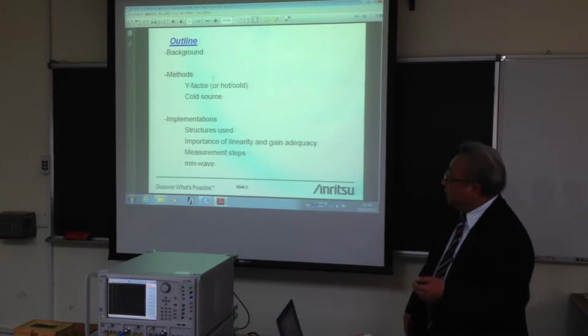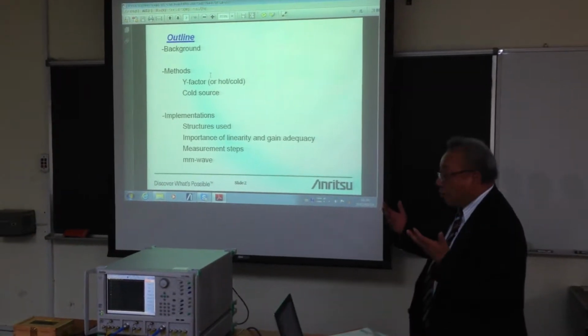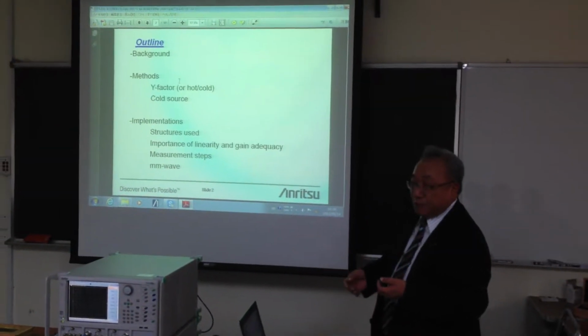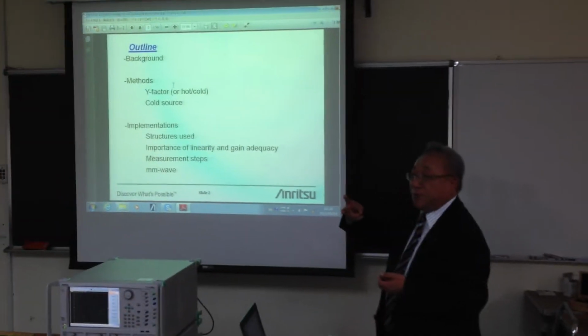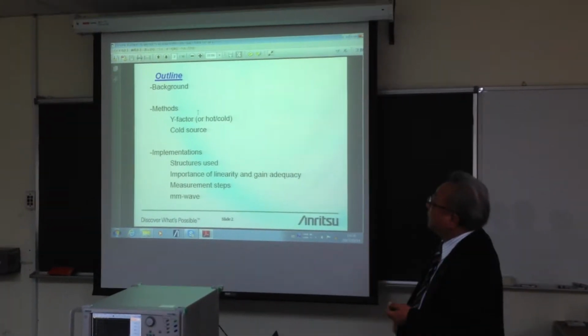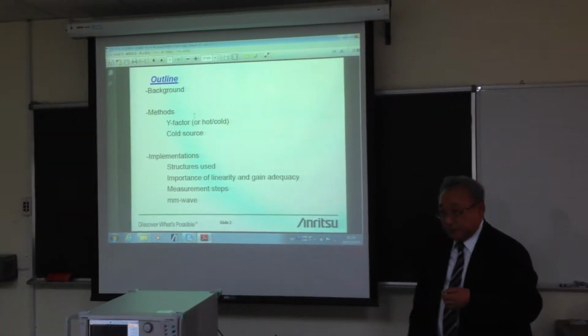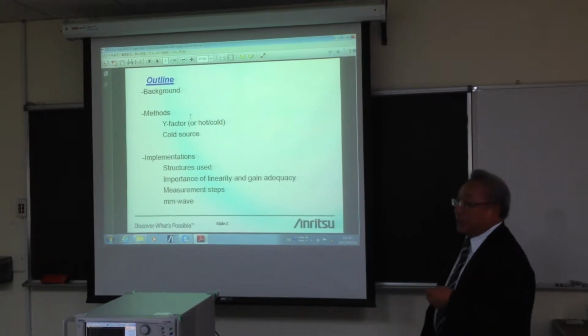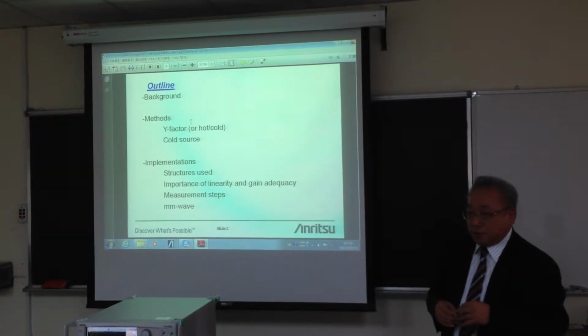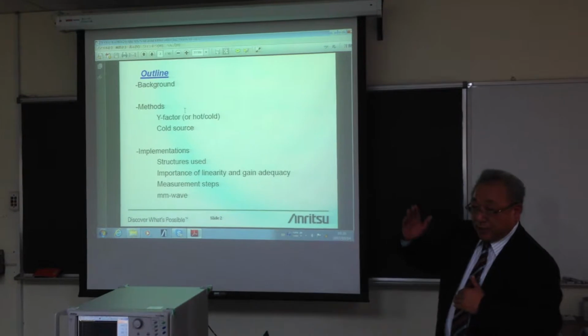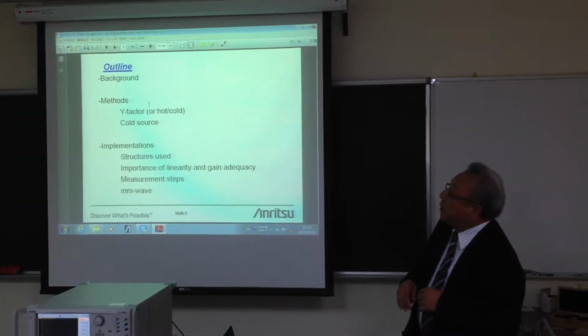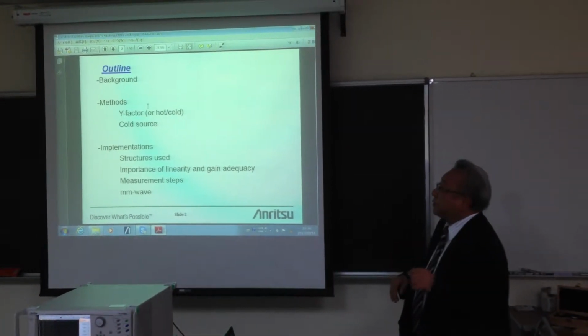Maybe you already know what a noise figure measurement method is. Currently, there are two methods in the market. One is the Y factor technique. That is using a noise source, hot and cold noise source. So you need an external noise source.